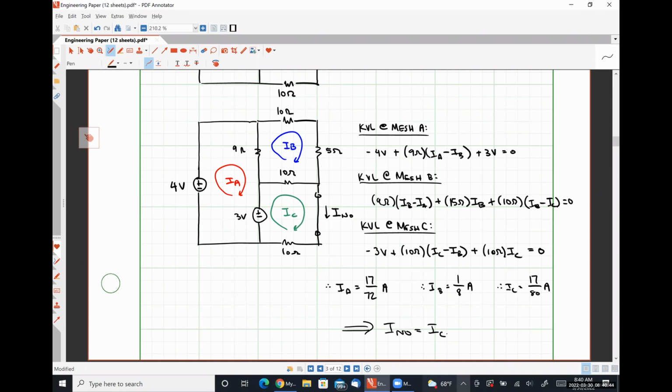Fantastic question. Okay. So because my Thevenin voltage was taken with positive polarity on the top, my Norton current would be flowing into that positive polarity term. Now, on your exams and things like that, I explicitly specify the polarity of the Thevenin voltage and the direction of the Norton current. On some of your homework problems, it isn't explicitly stated.